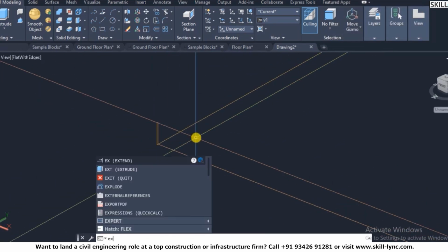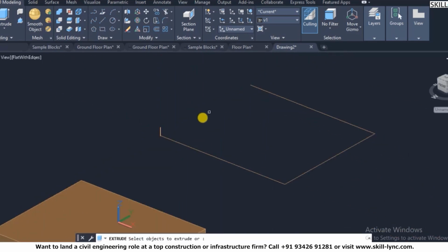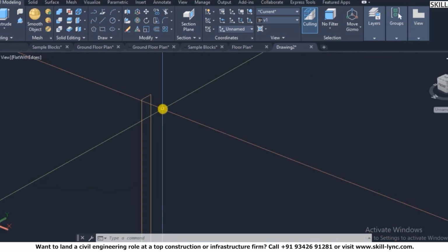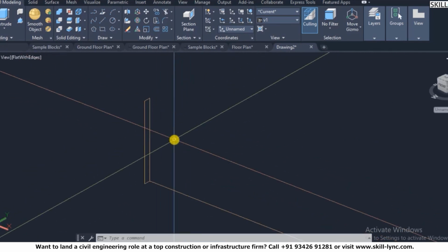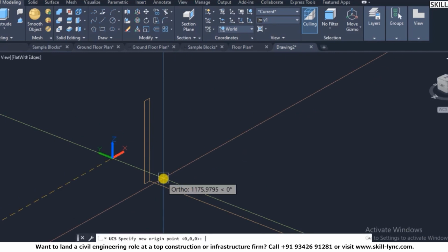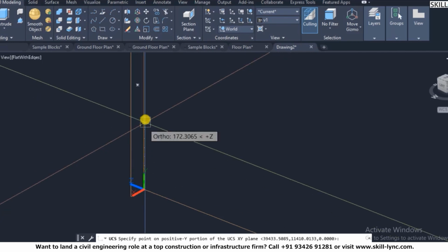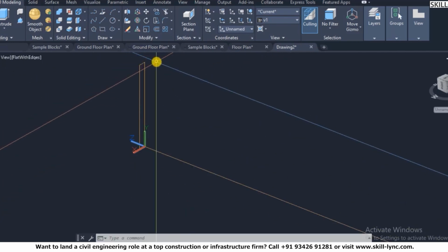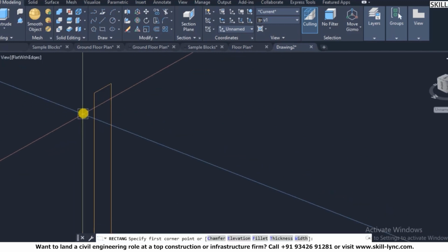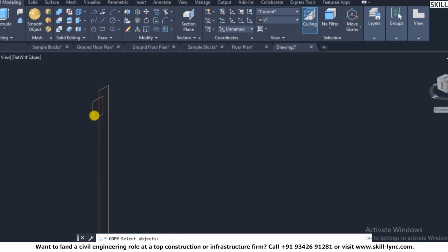So you extrude, or let's say delete this, you can use an extrude option, and you can select the profile. Now if I want to give a profile into it, so UCS world and UCS 3 point, now see what happens. So I'm just thinking that I should give a profile into it. Giving a profile is, let's say if I have some rectangles over here and I copy this down.